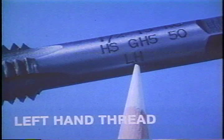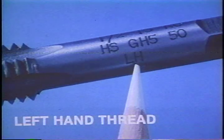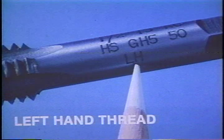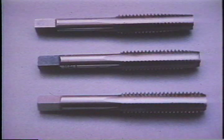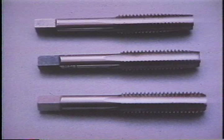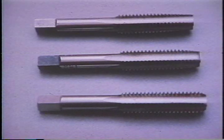If a tap has the additional lettering LH, it has left-hand threads and cuts in a counterclockwise direction. Now let's take a look at the kinds of hand taps and how to use them. The most common hand taps come with straight flutes and are made in three basic styles: a taper tap, a plug tap, and a bottoming tap.